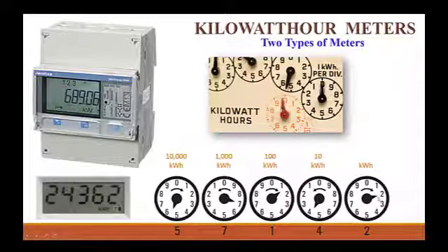And the rule of thumb here is that until the dial meter is pointing at a new number, you still read it as the previous number. So here I'm pointed at 2, so it's a 2. But in this case, I have left the 4, but I'm not quite to the 5, so I count it as a 4. And here I've left a 1, but I'm not at the 2, so I count it as a 1, and so on.